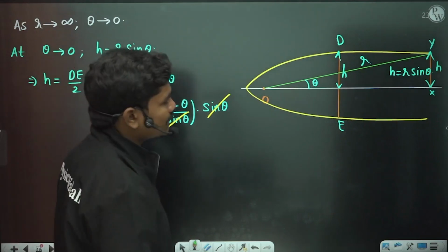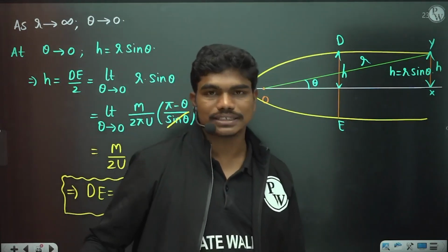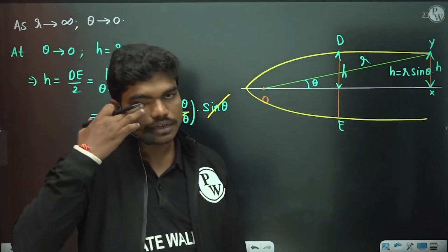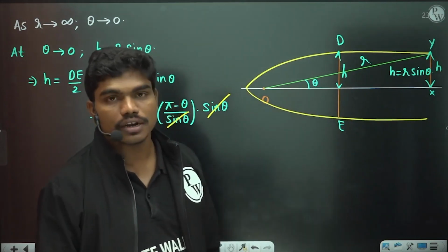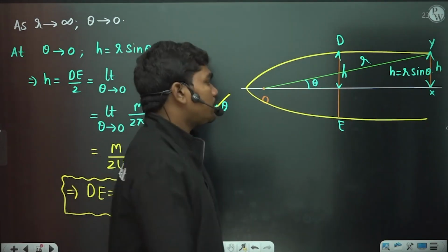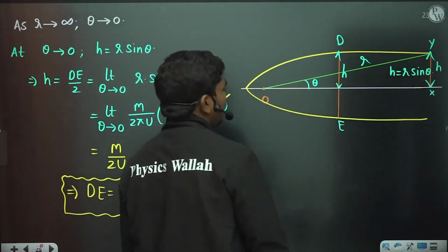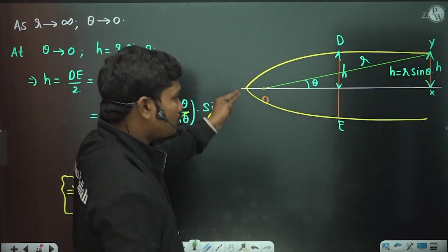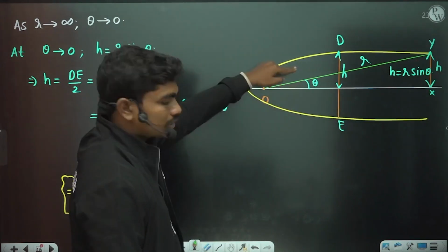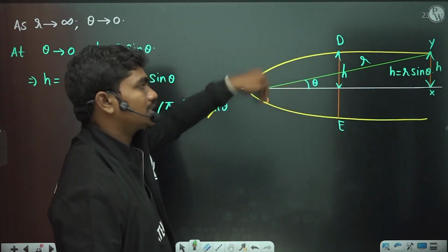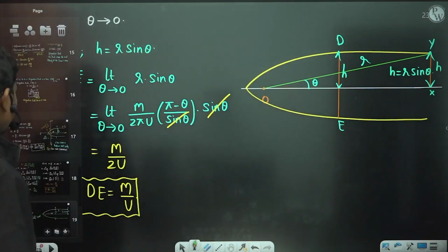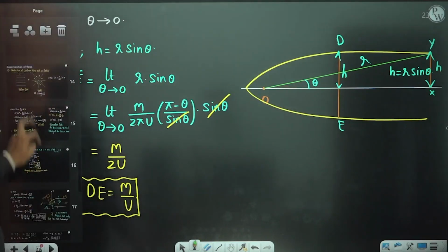So this is generally analyzed as the case of flow past a half body. Okay, flow past a half body, and this half body is called Rankine half body actually. Okay, you know why this is called half body? Because you cannot see the other end of the body, and since this is a streamline, flow cannot cut this streamline. This is assumed as some solid body actually.